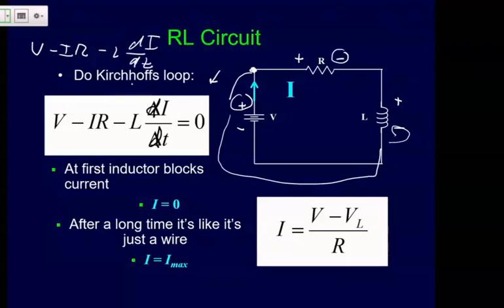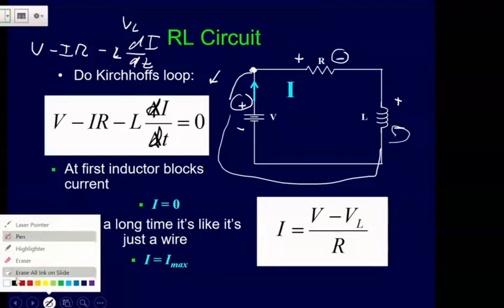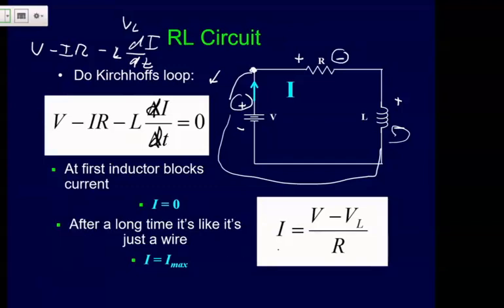And so we can go through and interpret this equation a couple different ways. We'll deal with the one later. But one thing that we can do is say, well, this whole thing here is my voltage over the inductor. And so I can take that and solve that equation just for my current. And we did a similar thing when we talked about RC circuits. And so the current is going to look like this here.